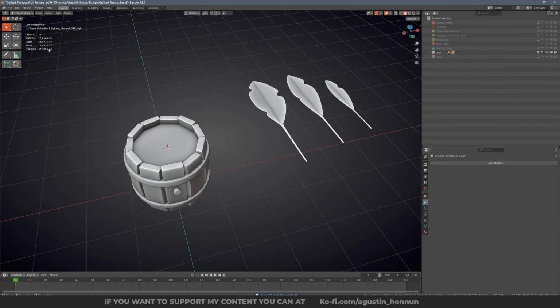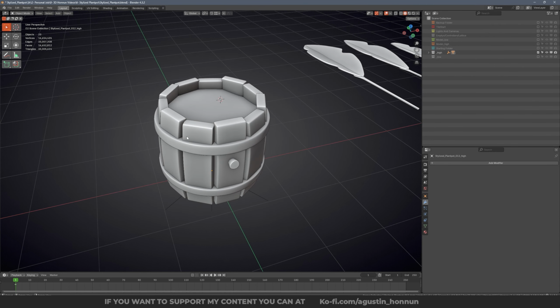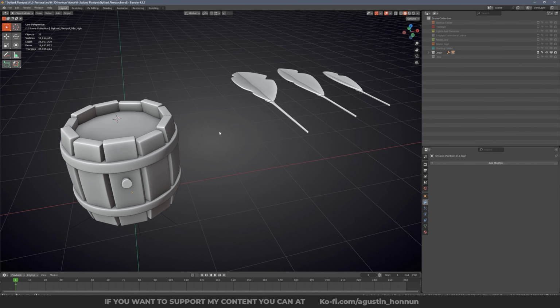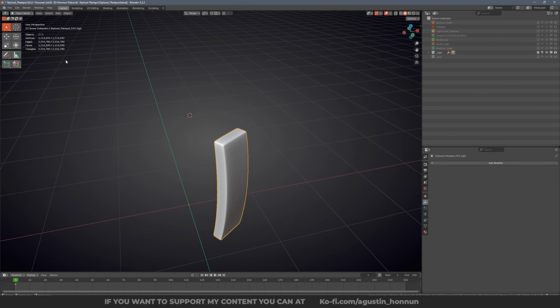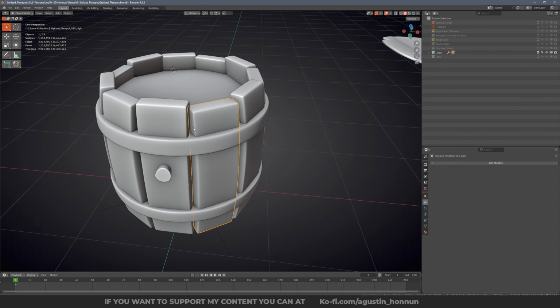We have 33 million triangles. You can be fine with this amount of triangles to sculpt since they are not one single mesh. If you have one single mesh with this amount of triangles, everything will be very laggy. But if you have a lot of objects here, we have 23 objects, each one of them is like 2 or 1 million triangles. This can be sculpted very smoothly.